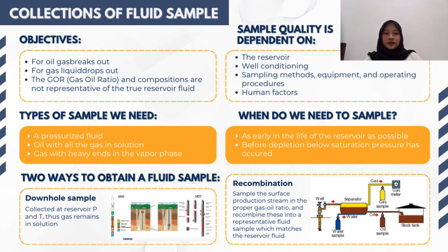First, fluid remains under pressure, or a pressurized fluid. To maintain composition as in the reservoir, the sample must be stored under high pressure. Second, oil with all gas in solution. If gas separates from the oil, properties will change and no longer represent the original reservoir condition.